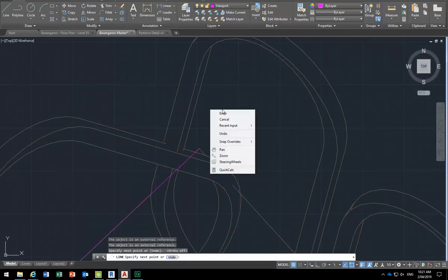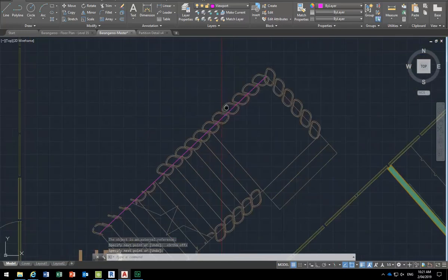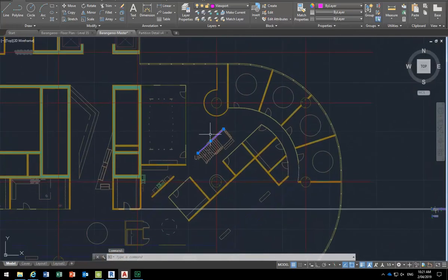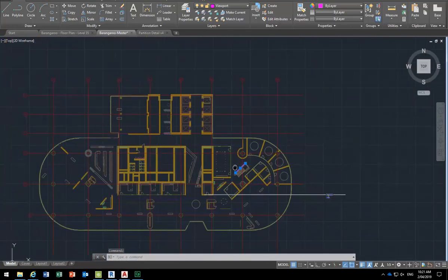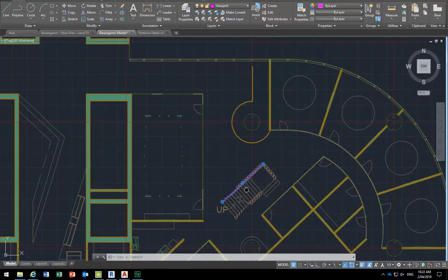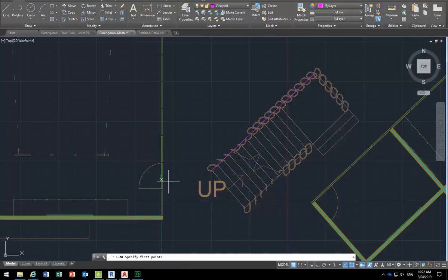If you work in some of the offices like the one people at Gaia work in, where all this was done, they would actually have another file, an Xref, that had the projection. So the section of the stairs would be in another file, and that could be linked into this file. That's a bit of a complicated setup. So instead of doing that, I'm just going to project off to the side here. So I'll just draw some more lines now at the angle that I want.